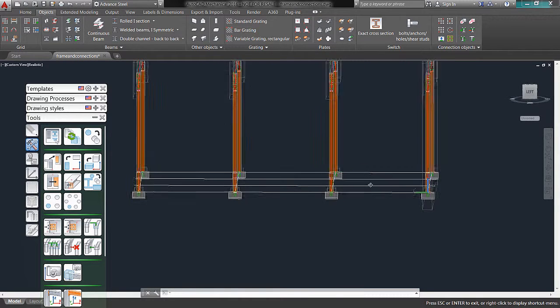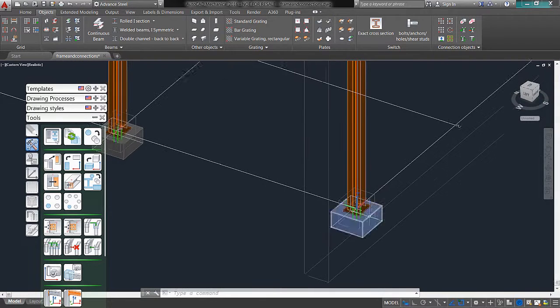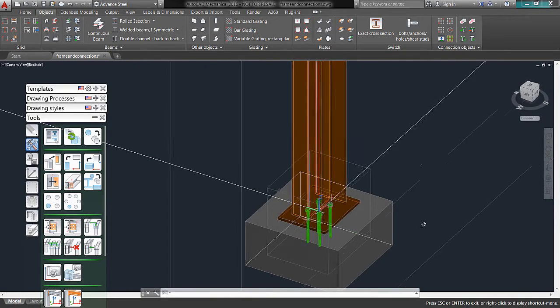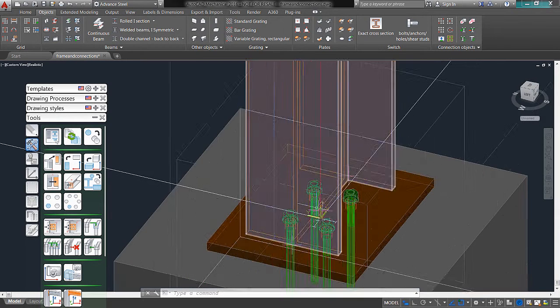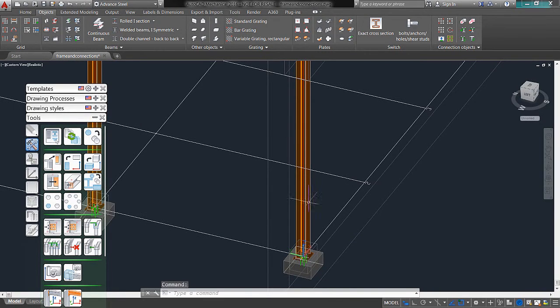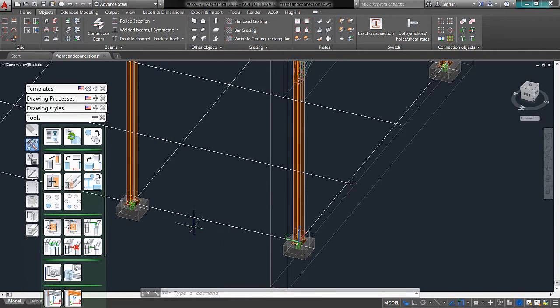I want to go ahead and add some bracing over here between these beams. And one thing I need to do is, before I start adding the bracing, I need to make note of my UCS here. It might be a little hard to see, but the bracing will be drawn basically, if you imagine the x-axis and the y-axis being perpendicular, there's a plane in between those two. The bracing is going to be drawn in on that imaginary plane. So what I need to do to ensure that I can just click and pick and place these braces in is I need to rotate my UCS around to where my y is facing up and my x-axis will be facing down this way along this path.